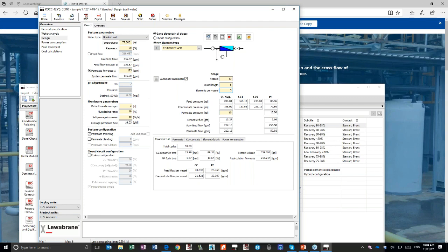And then during PF, I just like having the extra energy and turbulence in there to blast out the concentrated brine. So during the flush, you can actually dissolve some of the scale. If things have started to precipitate out, the low TDS flush helps dissolve that, but at the same time, the extra energy and turbulence to blast out that brine, and anything that wants to precipitate out, is beneficial.